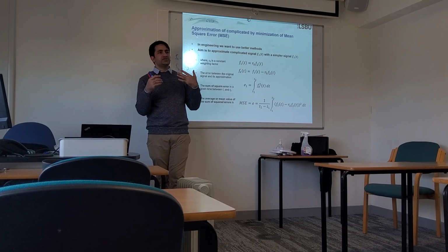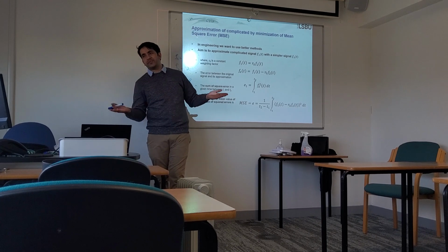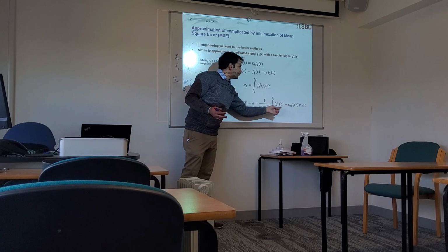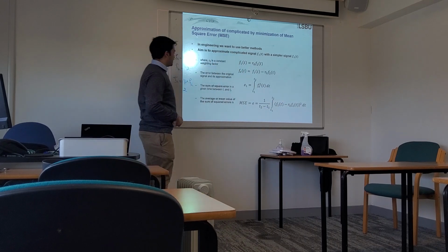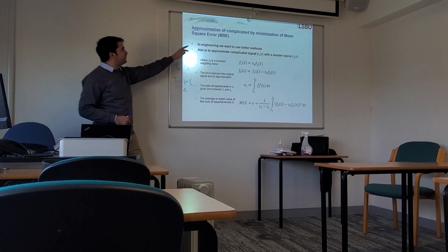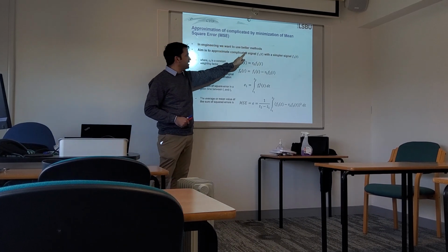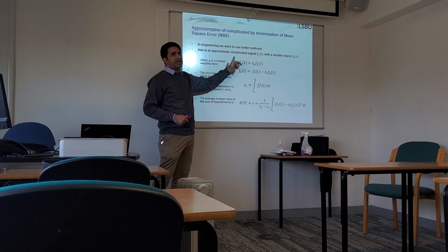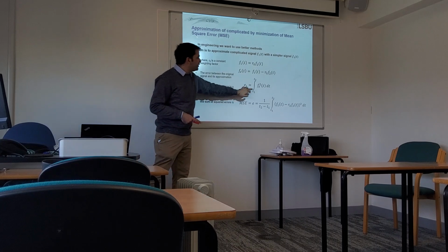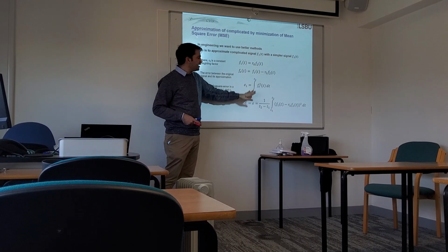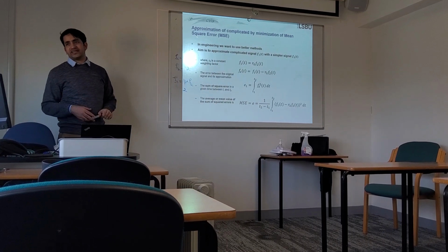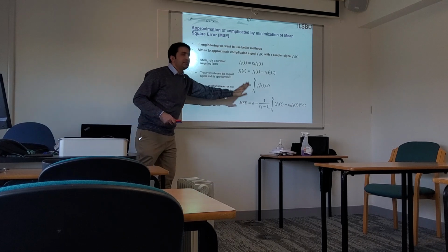You take the function, you integrate it, and you divide it by the whole time period. Here your function was the square, so you put in the squared function and then integrated it. So we have achieved mean square error: starting from the original function, then the approximation, then we move towards finding the error, and once the error was found, we squared and summed it, then divided by time. We have taken the average, or the mean. So this equation is mean square error.